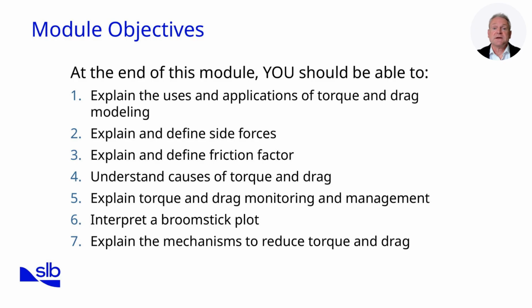In this final submodule on torque and drag, our focus shifts toward practical applications, specifically monitoring, managing, and reducing torque and drag during drilling operations. By the end of this session, you should be able to, first, explain how torque and drag are monitored in the field. This includes understanding which parameters must be measured, such as pickup and slack-off weights, rotating weights, and surface torque, and how these measurements are taken consistently and interpreted accurately.